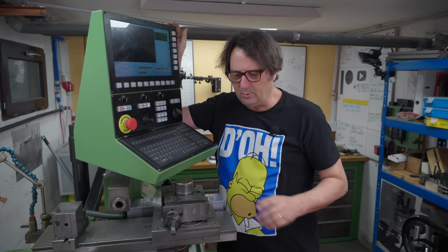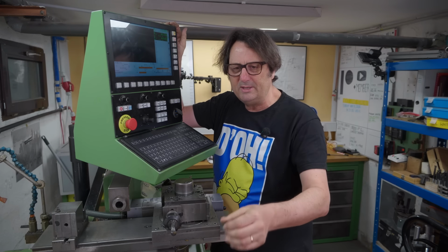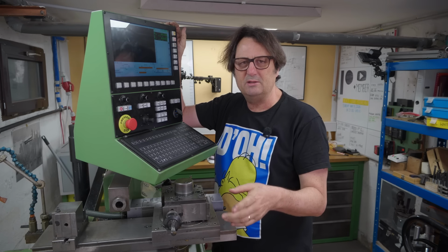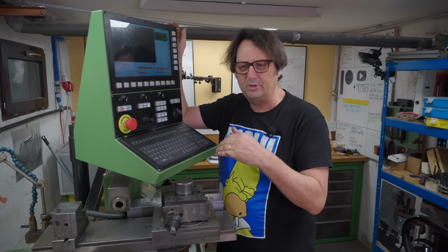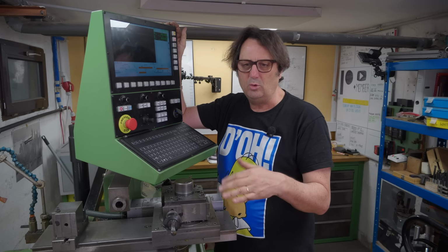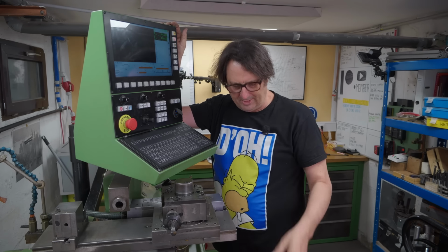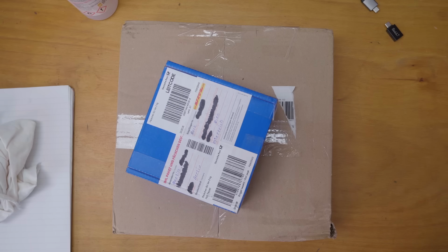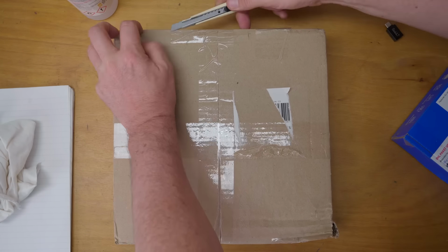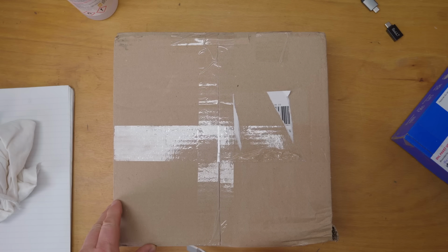I'll have a look and see how I can inhibit that. Probably the best way will be to do it off spindle speed and make sure I have had a completely stationary spindle or near stationary spindle before the switch occurs, which I thought I already had, but obviously need to recheck that.